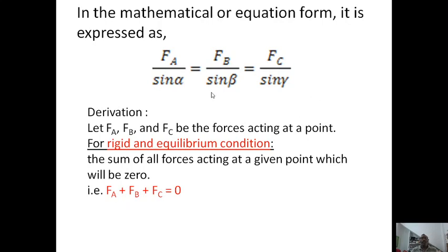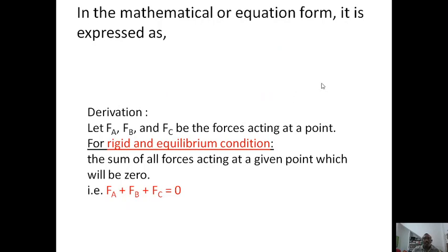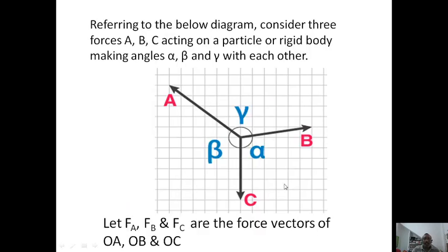This is the mathematical formulation of the forces. In the earlier figure, you can see a graph, because the forces can also be expressed geometrically. You can get these values by drawing. Fa, Fb, Fc can be drawn graphically by taking some scale, like 100 Newton equal to 1 mm, according to the intensity given.